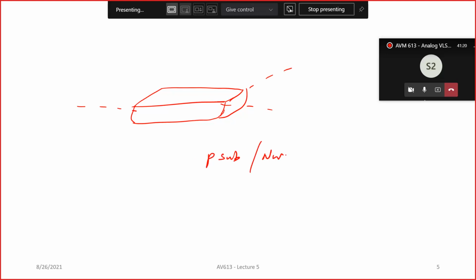So for example, if you take a diffusion resistor, this diffusion resistor and this P sub is going to form some diode, and this diode is going to have some capacitance. Now all these resistors will also have a third terminal which is basically a substrate contact. This will be a substrate terminal. So what will you have? Along with your resistor, you also have a little bit of distributed capacitance with your substrate. So that is what you basically get. Now these are all the parasitics that are there, and you should be aware of these things when you are doing your design.